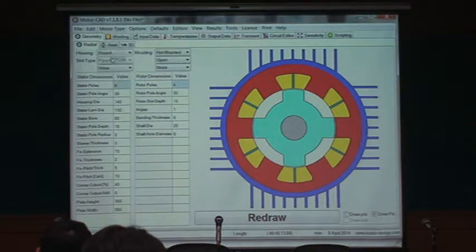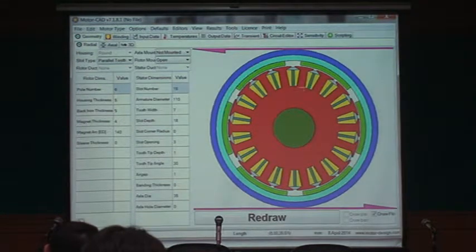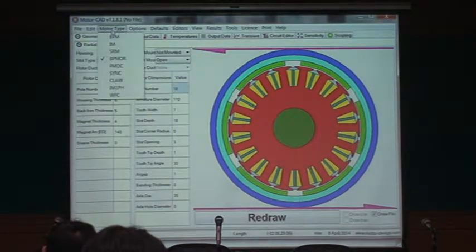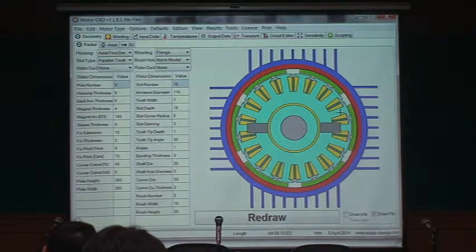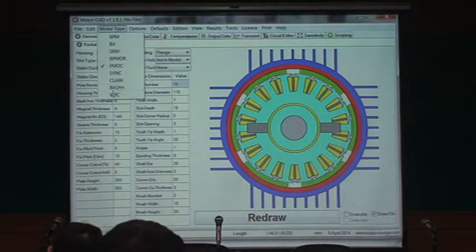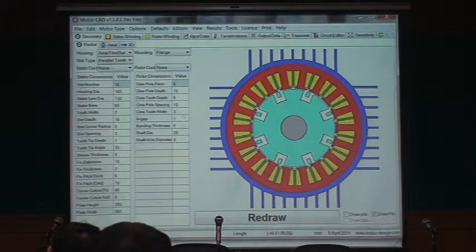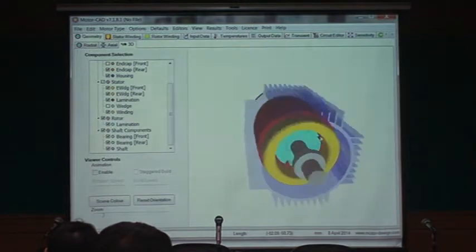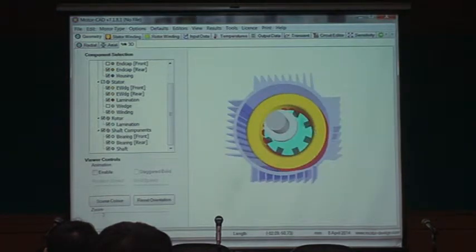Motor type, we have outer rotor, all of those things. So this is just a regular brushless machine, but the rotor is the one that is turning. And I'm going to go a little further. We have the brush machine, so now we're going to have brushes also associated to this. And then maybe another type of motor, the claw-pole machine. So this is essentially a 3D type of machine. If I look at the 3D pictures, it's not as clear, but you can see the claws that come from the other side. Just think about a claw type of structure. And this is a permanent magnet machine we're seeing.